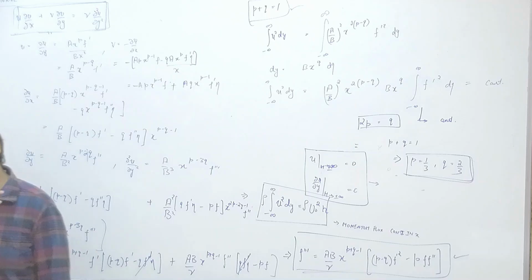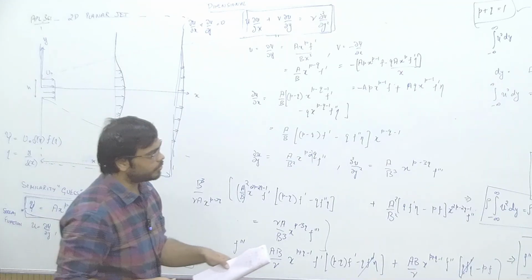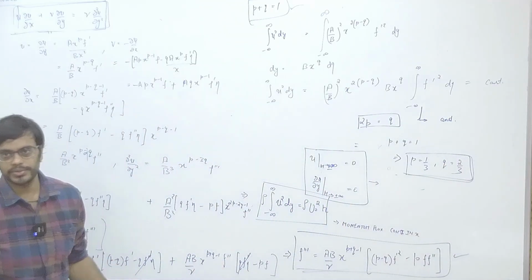And this goes back to our discussion earlier, when we were doing the non-dimensionalization, about how we estimate this length scale delta. What I had said is that in case of a boundary layer, this delta is a diffusion thickness, but in case of jets, this delta is not quite the diffusion thickness; it varies with x as 2 by 3, not half.